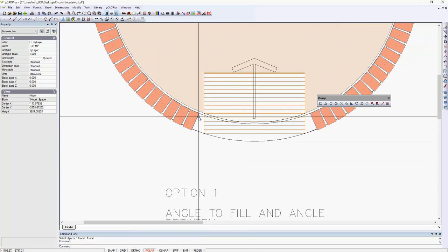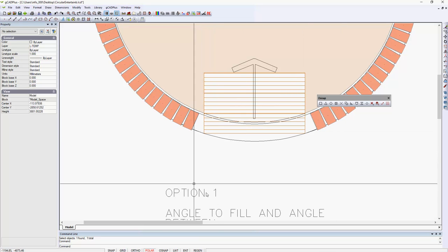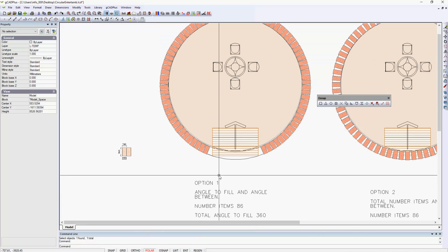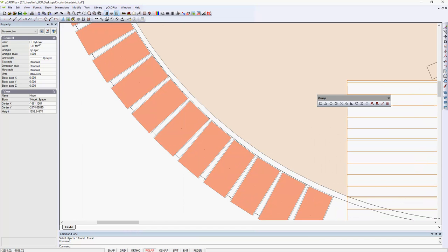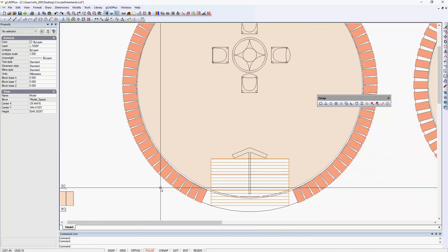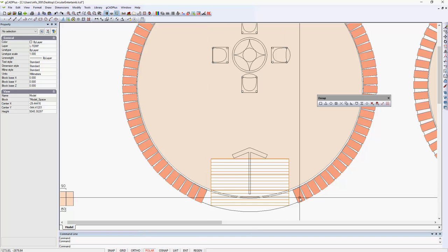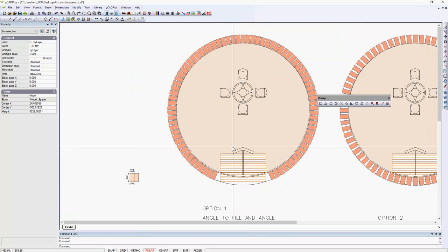We still have to do a cut and put one in there and another one over here. So I hope that helps a little in using the array command to perform a function such as this. I do have a point in the center of the paving brick wall, and I can go format, point styles, and change from pixel to none, and those points disappear. So 2 cuts, and now your construction team can build that job with a degree of confidence.